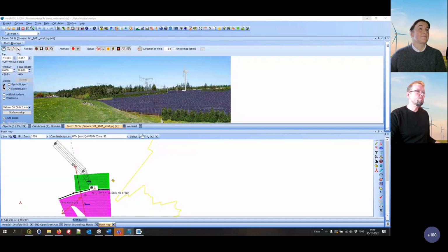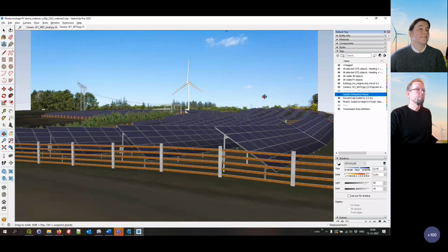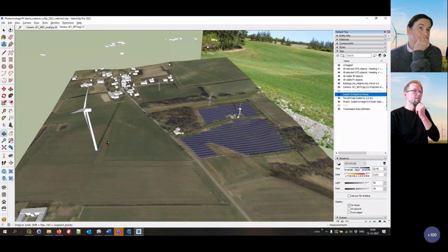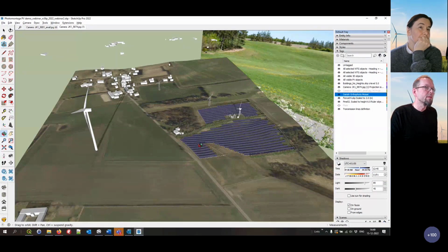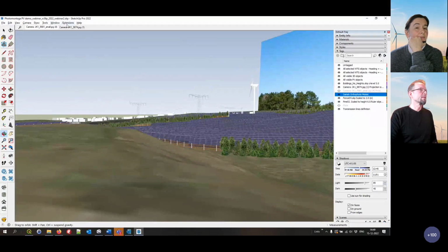If you want to show shadows correctly in a photomontage, from a VTG or something like that, you can see now when I turn on shadows, it takes a little while for it to show up, but that is because we have so many objects casting a shadow. You can see the shadows from the PV panels, and from the trees, and also from the transmission lines on the surface and stuff like that. But if you want to get these into the windPRO photomontage, there is actually a kind of workaround where you can save your photo here, from that might not be a good example.